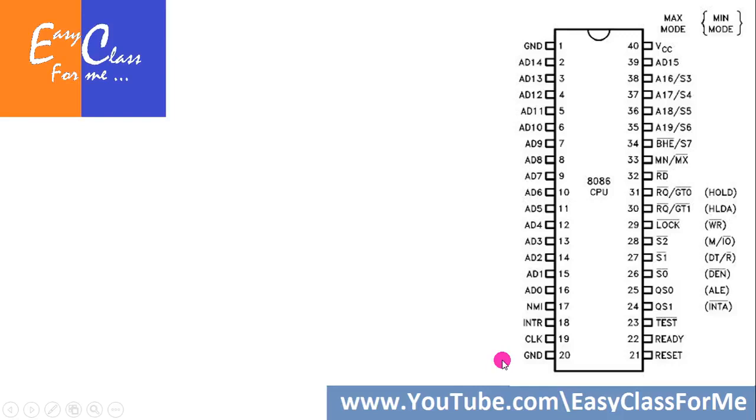So the advantage of time division multiplexing the address and data bus is that the same pins can be used to transfer address and also data. But since the address bus is of 20 bits and the data bus is of 16 bits, some of the pins of the address bus will be left.